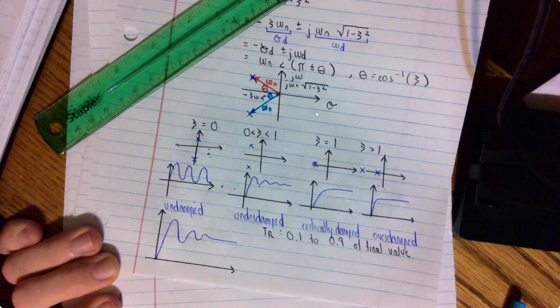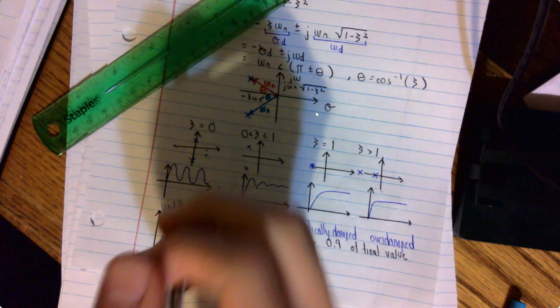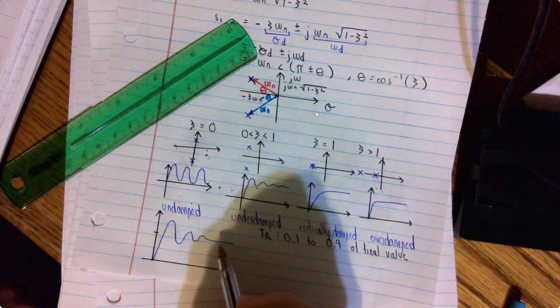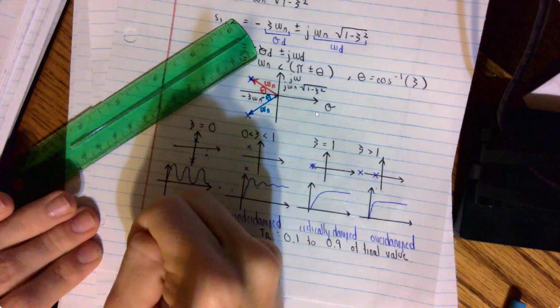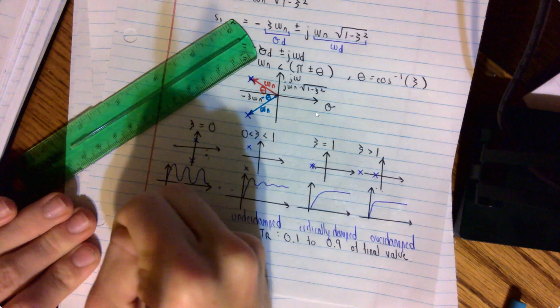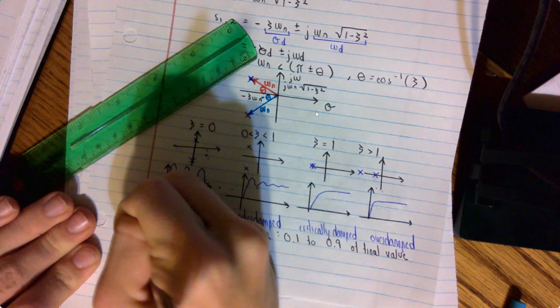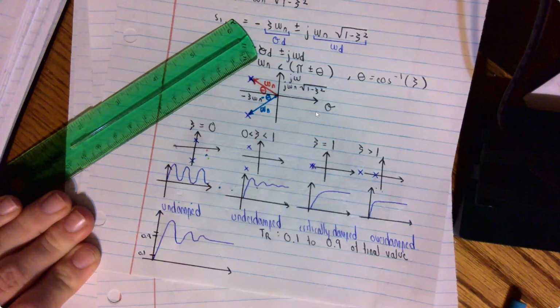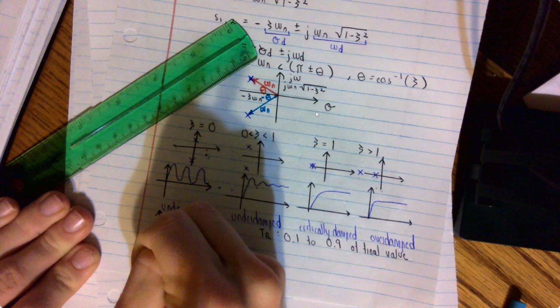And so if we're to calculate the rise time here specifically, our final value is going to be at this point right here. So that's our K, the final value that we approach. From 0.1, that's going to be about here. And then 0.9, if this is the final value, is going to be about here. So that's 90%. I would say that this would be about the rise time in between those two intervals right there.